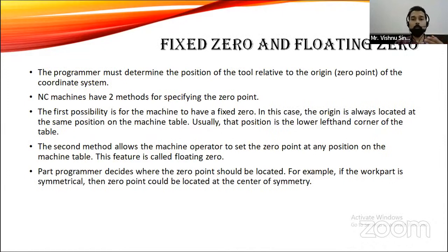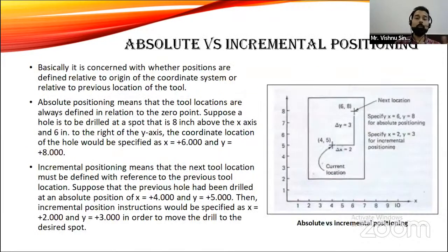Then we have seen fixed zero and floating zero. Both these terms are related to the origin. In one case, my origin is always located at the lower left corner of the workpiece, and in the other case, we can locate our origin at any point on the workpiece.